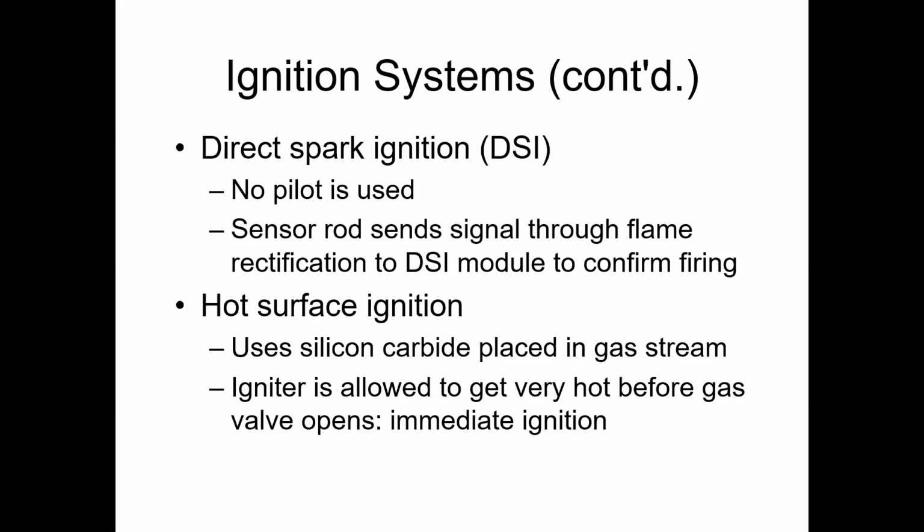But when it's in a common location, that's when it gets really annoying, and people will opt for a hot surface igniter if they can. So they're really, really common. They're easy. I always kept a bunch of HSIs on my truck. It was the most common repair. Like I said, in wintertime, that was my number one. Summertime, capacitors. Those two got me through a lot.